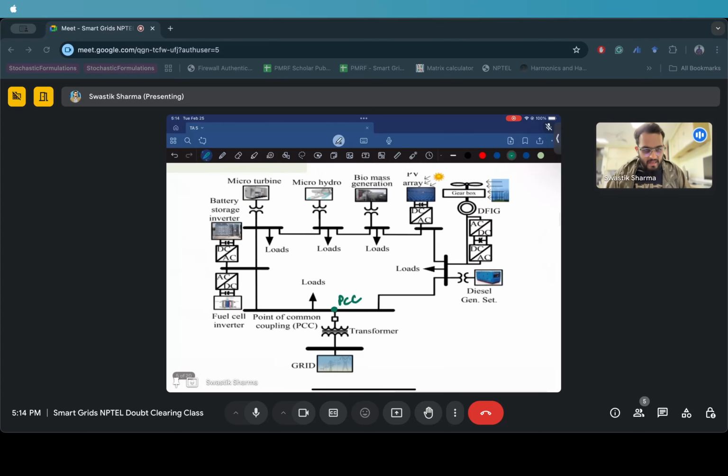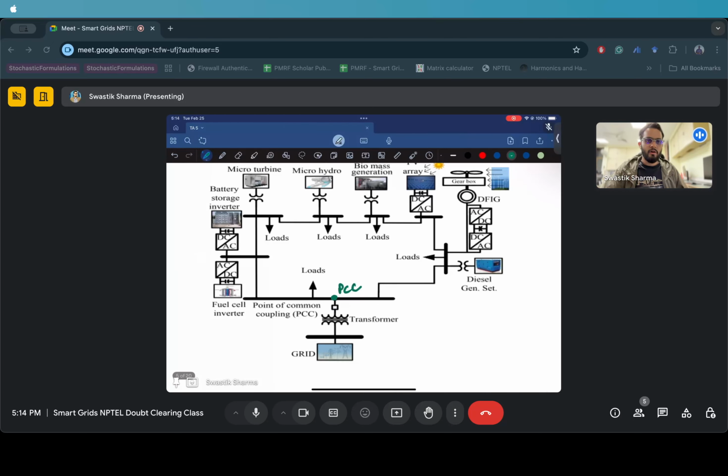It may so happen that when it was islanded, or behaving on its own, there could be some frequency related to how these loads were functioning, and the main grid will have some frequency, right? Both of them are not interconnected right now, and they can have separate frequencies too. Now, at the time of unintentional reconnection, what happened? These two frequencies are out of sync. Let's say this is at 49.4, which is quite low, and this is 50.3, right? And you're trying to reconnect at this frequency, right?